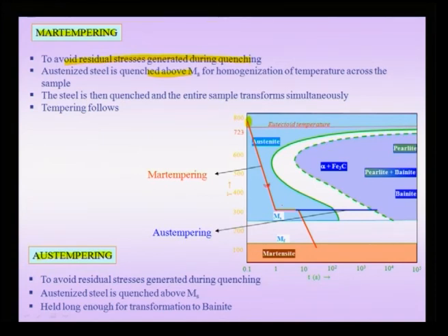temperature, because when we do a normal quench, for instance, suppose I take a cylindrical sample and quench it, the surface faces the quenching medium, and that means that this is cooled and the interior is not cold, and in this process residual stresses are generated. These residual stresses are the thermal residual stresses, which is in addition to the residual stresses produced directly due to the transformation itself.